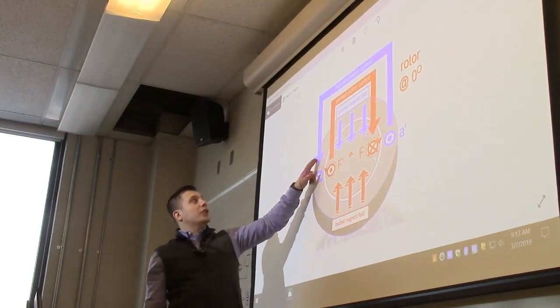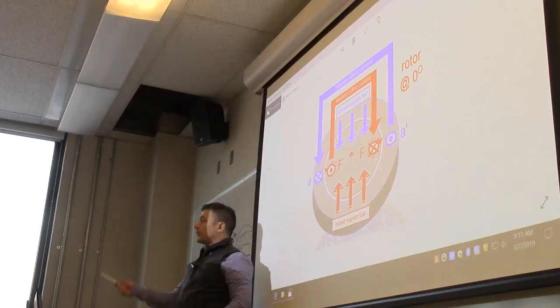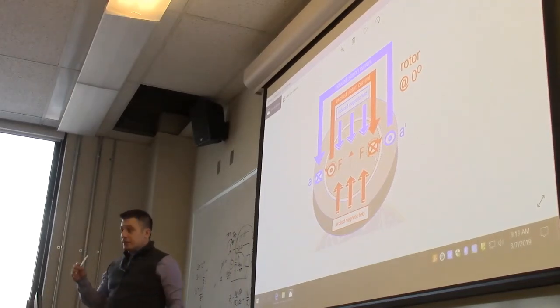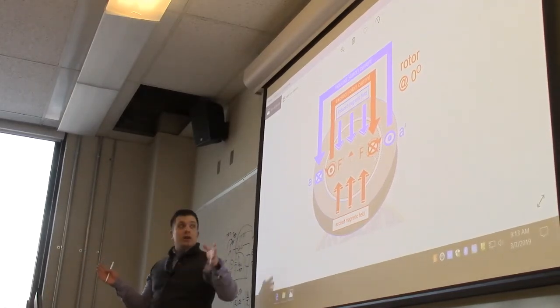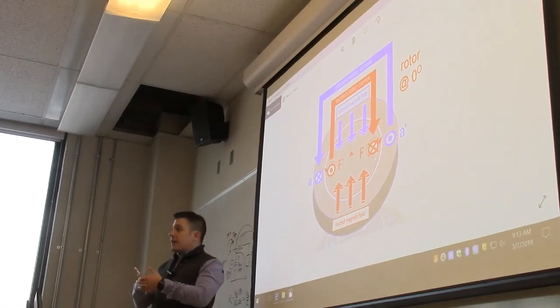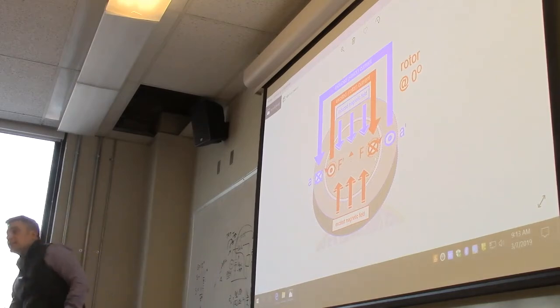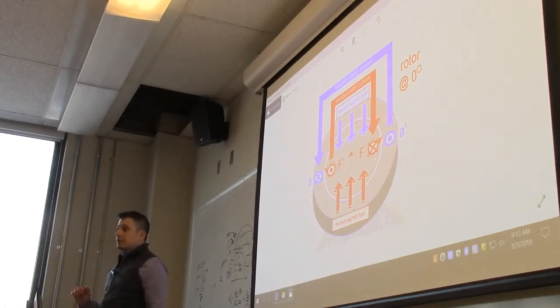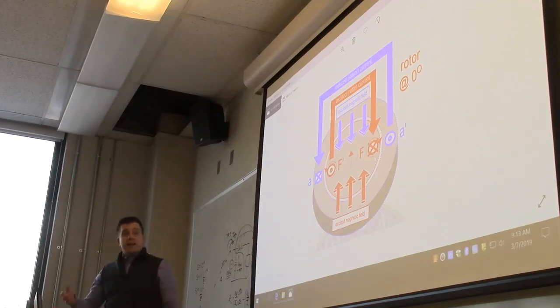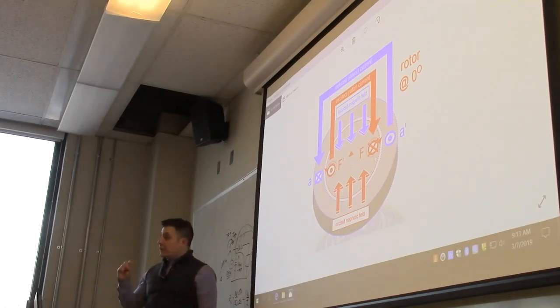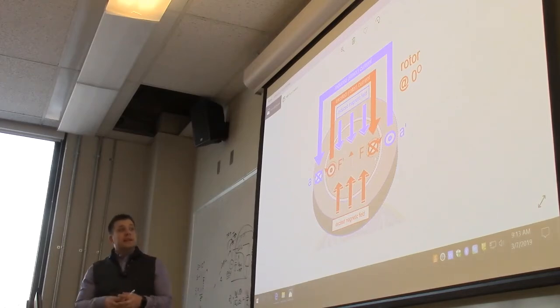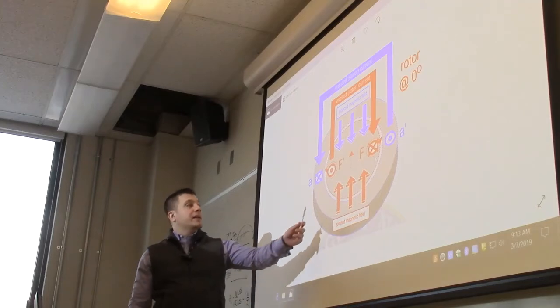So when you think about the current flowing on the stator windings, the direction of that is such that the induced magnetic field and the excited magnetic field net out. It's sort of like when you push against the desk, the desk pushes against you with that same amount of force. So when you excite this magnetic field using the field winding, the current flowing through the stator winding creates a magnetic field that opposes it. Okay? But it's really the power flowing in one direction, right?